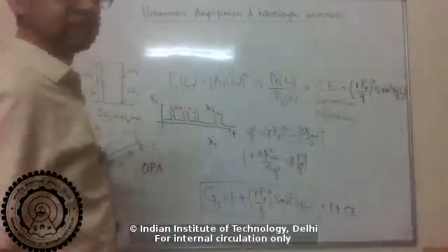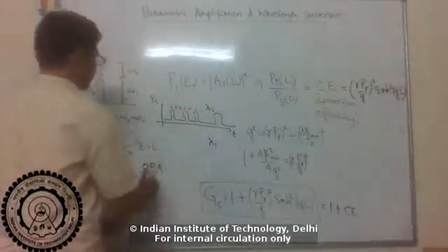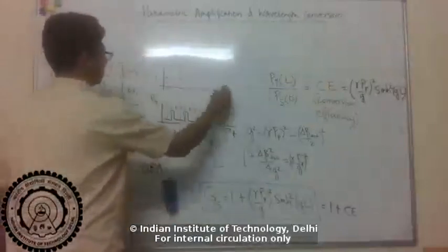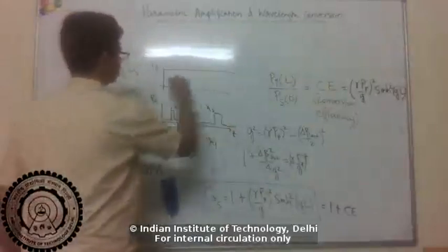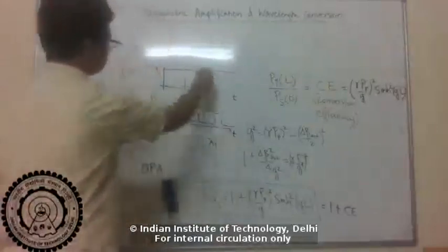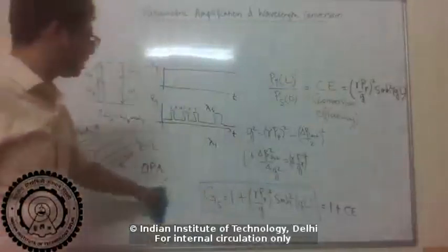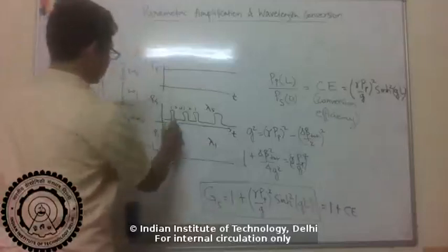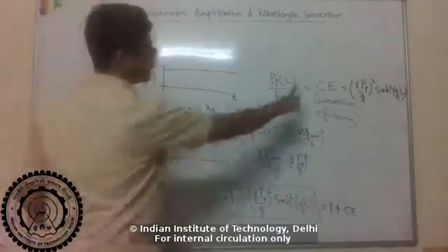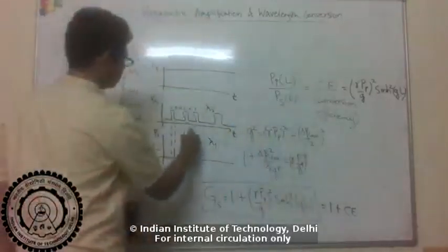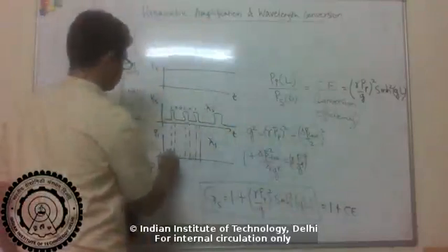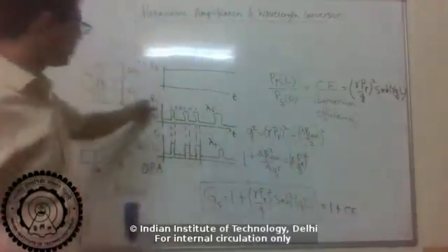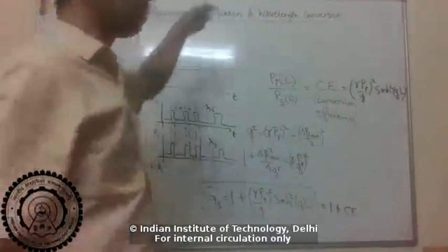Then I can use basically this four-wave mixing process. For example, assume I have a strong pump. Let's say I send in a CW pump, which is strong. Then due to the four-wave mixing interaction, what will happen? The signal will get converted to idler. So whenever the signal is there, I'll get some conversion, and I'll basically convert this data onto a different wavelength. That's called wavelength conversion.